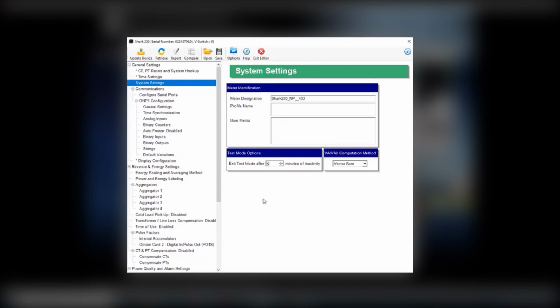So here, when you take the meter out of service, you test the meter, you inject voltage and current into the meter, and you apply it to a standard, and you make some comparisons to see how the percentage registration is, to see how far it is off. I'm kind of explaining calibration in a quick couple sentences, but basically, when you put the meter in test mode, it allows you to test the meter, and the longer window you have to test, the more time you'll have to test the meter without the meter kicking out of the test mode and interrupting your test process. So that's very important. That 10 hours is a very good amount of time. Some people take an hour, some people take 3 hours, 4 hours to do a calibration. So you want to set that based upon how you test the meter or who is testing the meter.